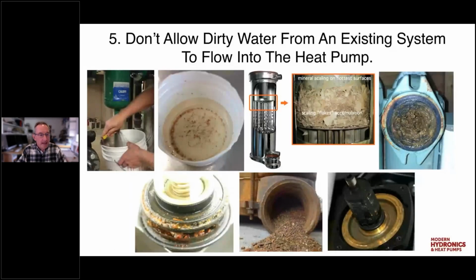All right, let's go back inside. So here's some photos just to show what can be found inside a hydronic system, especially an existing system. You can see here, it looks like somebody's been panning for gold, but those are just copper flakes, copper chips, and dirt that have been flushed out through the bottom of a dirt separator.